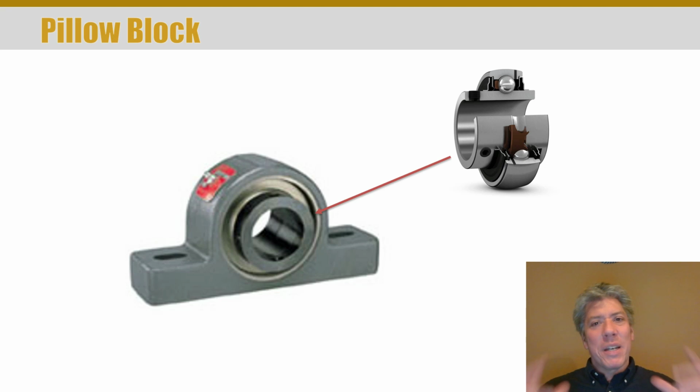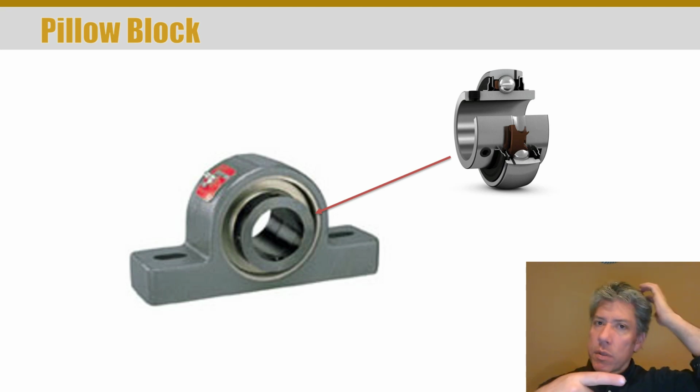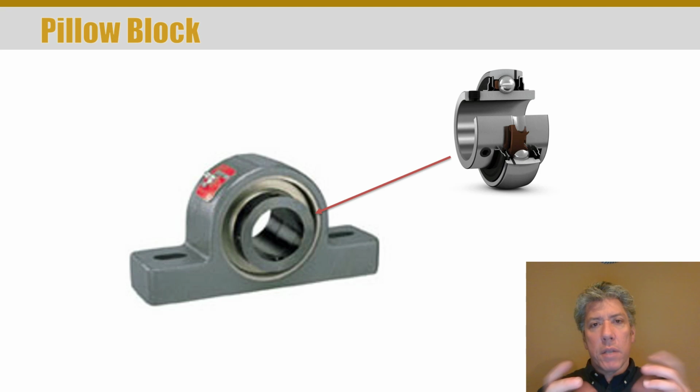But if you think about building a go-kart, you weld together the frame, and then you want to attach, say, a solid shaft for the rear wheels, right? Well, that shaft is a live shaft. In other words, the shaft turns. It's not a dead shaft. Now, some go-karts do have dead shafts. It's just basically a stud that sticks out. You put the wheel on. The wheel has bearings, and it rotates around this dead shaft, and you have a chain that drives the sprocket. But in the case of her cart, it's a shaft that goes across and actually drives both rear wheels rather than just one, and that's the advantage.